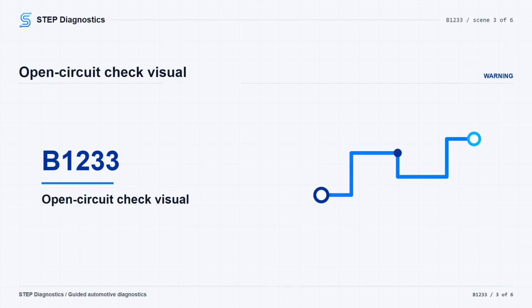Turn the ignition switch to LOCK (0). Disconnect the climate control unit 32P connector and the air mix control motor 7P connector. For both 2-door and 4-door checks, that setup is the same. Then check continuity between the specified test points for the AMDP, S5V, and sensor COM lines.